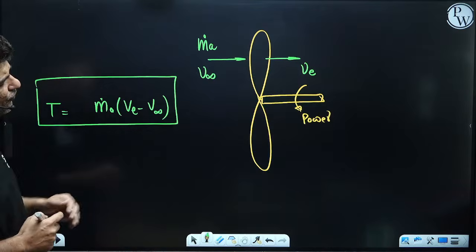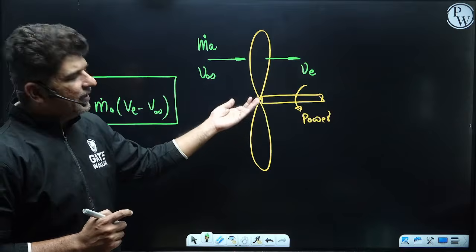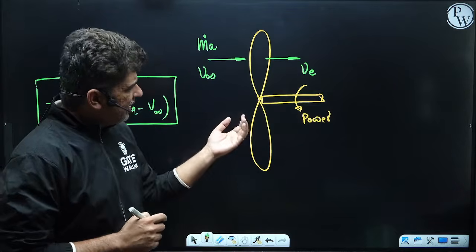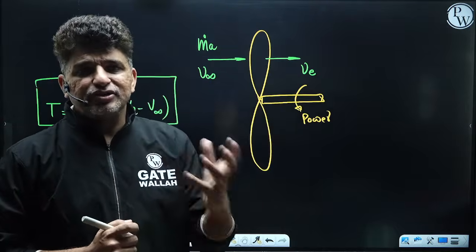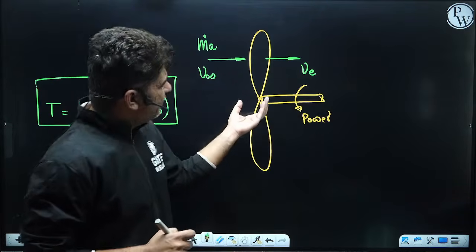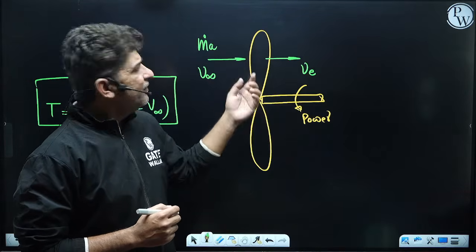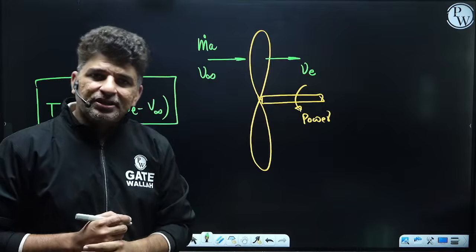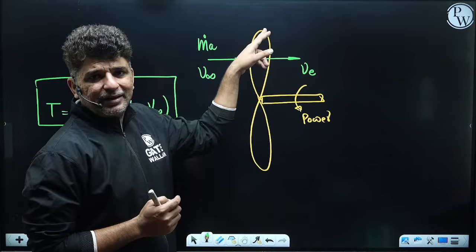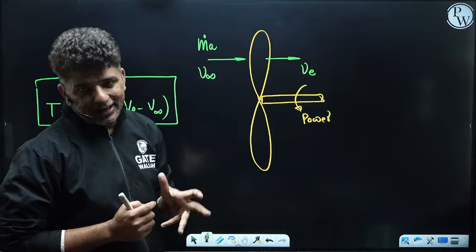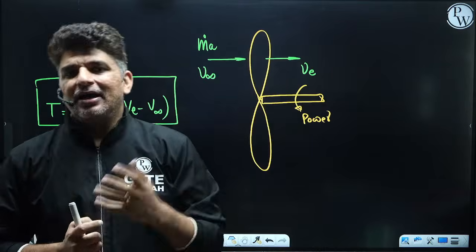Now let's move to a much more complex variant of the turboprop. You see, these turboprops are really good engines, but they have the problem of lower efficiency whenever the tip speed reaches Mach number 1. Whenever the speed of the propeller tip becomes sonic, they lose very high efficiency.